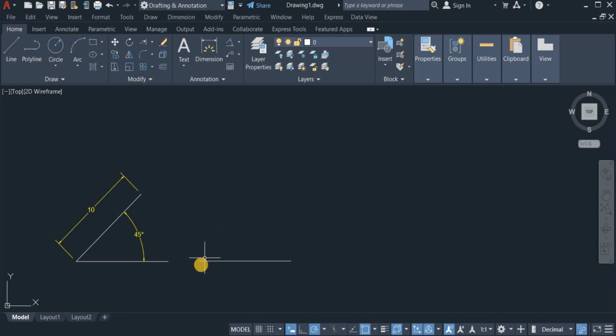Now I'm going to draw a line from this very point and make it snap at every 15 degrees. You can see the long green line projection there, indicating that the angle has been hit. If I click on the tab button to switch to the angle, you can see that it shows 15 degrees. Now if I move the cursor up, the angle has changed to 30 degrees, which means it has added another 15 degrees.